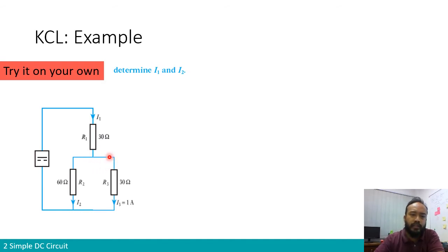What we need to do is figure out one of the currents between I1 and I2. Here you can recall the lecture of last week, where we looked at the parallel configuration like this. As a result, we found that we can create what we call a current divider using a parallel circuit. If we know the current I3 and all the resistances R1, R2 and R3, we can calculate the ratio of the current divider and therefore find the input current. So let's have a look at the answer.